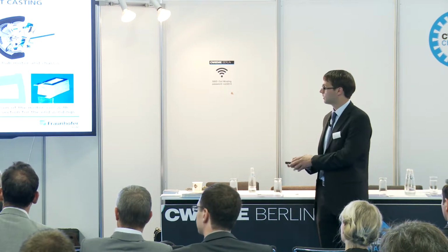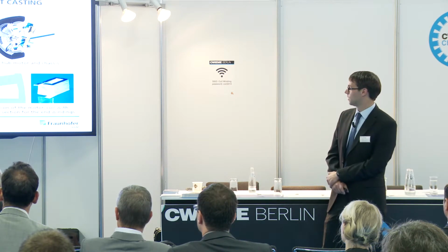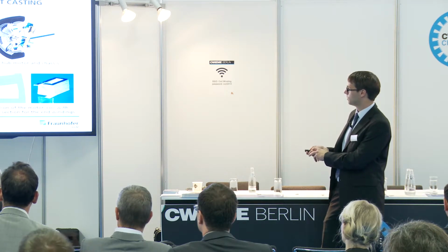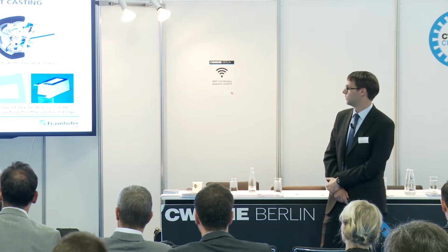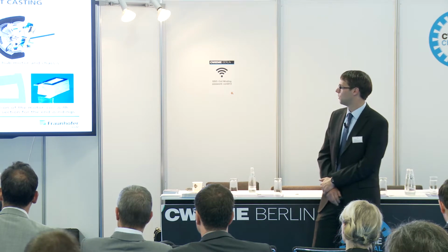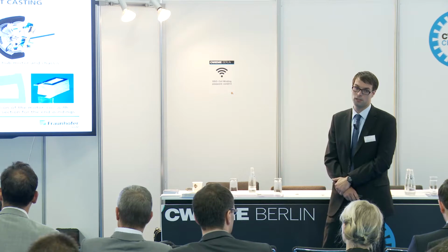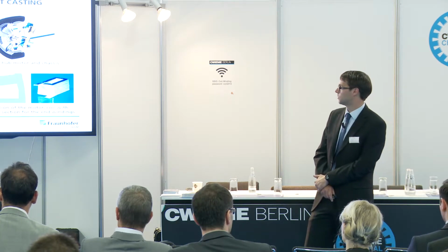The realized coil has 15 turns, a conductor height of about 1.5 millimeters. We increase the length of the end windings to reduce thermal hotspots, and the length of the coil is about 60 millimeters. This is a Fraunhofer project where we realize the machine, and we will test it by the end of the year and publish test bench results of this machine.